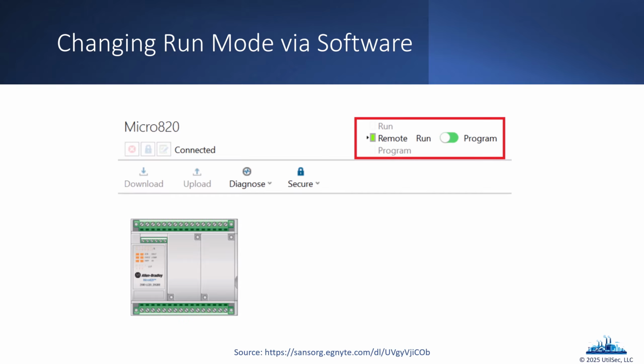And then with my paper, and the project I was working on, if you bumped out of run mode, then an operator would get an alert that says, hey, this Micro 820 PLC just bumped out of run mode. You need to investigate, see what's going on. Because we just want to make sure it's not an attack.